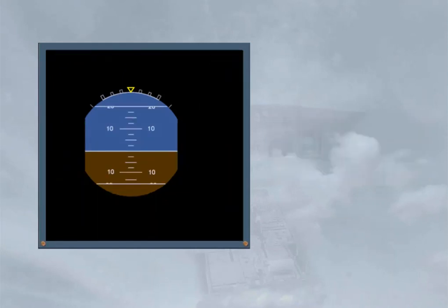Attitude information is shown at the center of the display. The attitude indicator works in the normal sense. The pitch scale has white markers, as shown. Beyond 30 degrees, large red arrowheads show the direction to move the nose in order to reduce the pitch.